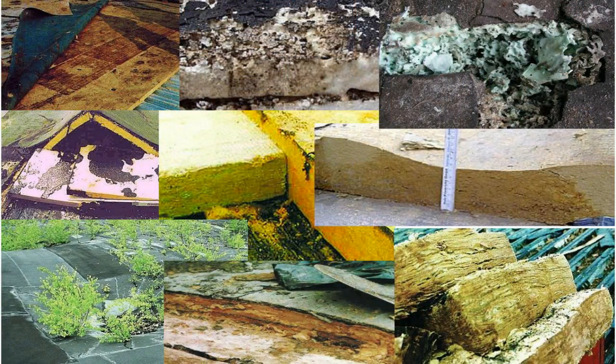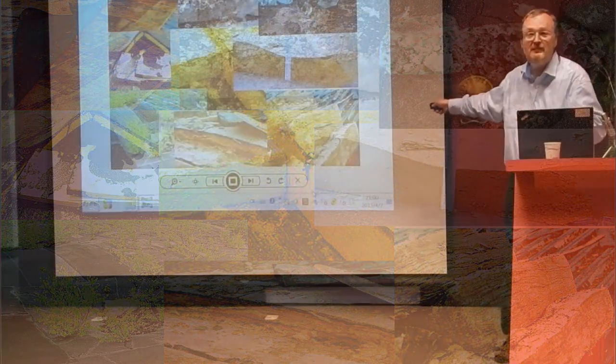All our flat roofs have insulation. And in all insulation we have condensation because of the bad behavior of all the insulation material and the facades, in all parts of the facade and of the roofs. And all is rotten. And everywhere the water will come in, not because the upper layers are bad, the reason is the frost and the water reactions in the insulation. So if you have only bituminous layers on concrete, it's much better. But in Germany we are forced to have insulation, and this will make all our roofs rot.